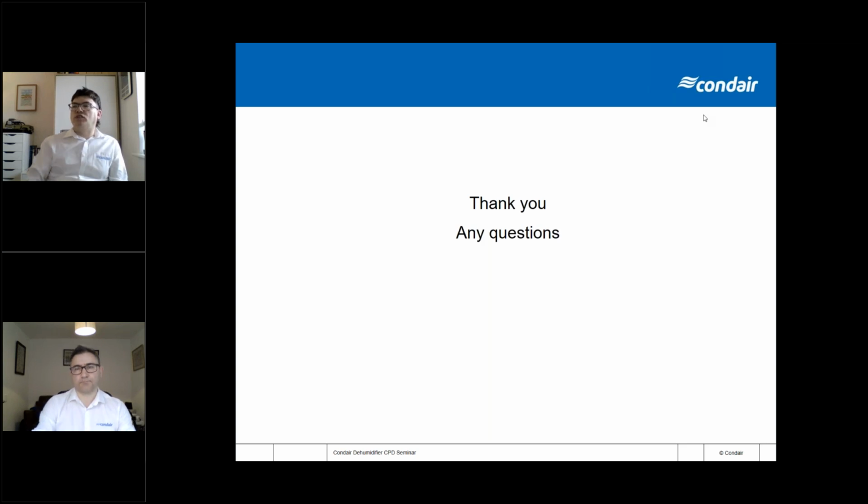Okay, we'll do two more questions, so I'm conscious of time, everybody. First one being, do you always need to pre-cool the process air before it enters a desiccant dehumidifier? Yeah, that's a good question. It very much depends on what you're trying to achieve. If you're trying to achieve a lower condition, then pretty much we know that we're going to be following that line of enthalpy down the chart.